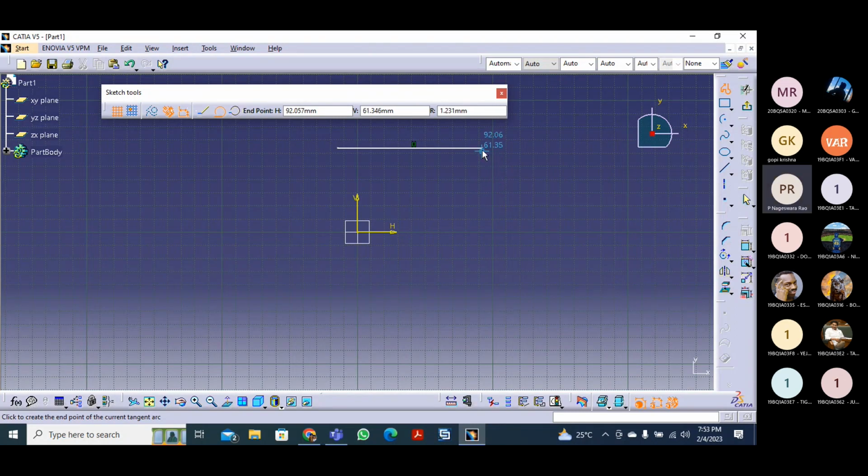When these two points are coincident, when they lie on the same line, the color changes. Like this, we can identify. See here, now the color is white. When you move this point, it changes to the exact semicircle because this point is coincident with this line. They are on the same line. So automatically it shows a color so that we can draw very easily.